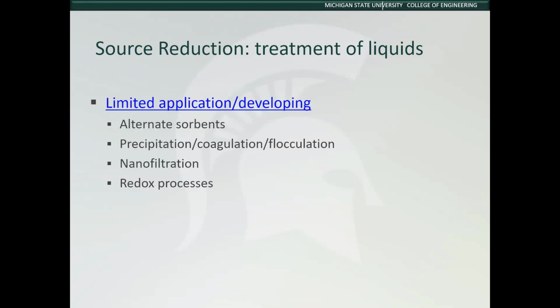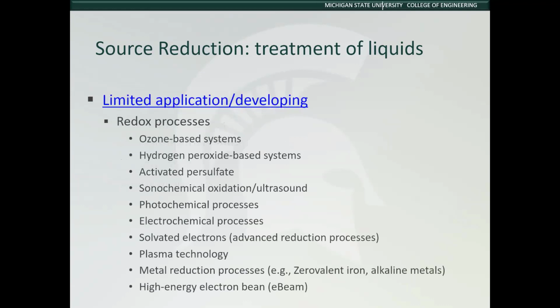We don't have time to consider all of the processes used for the treatment of liquids, but some of the ones that are in the developmental stage are alternative sorbents, conventional water treatment processes, precipitation, coagulation, flocculation, nanofiltration, also a pressure-driven process that doesn't operate at as high of pressures as reverse osmosis, redox processes.